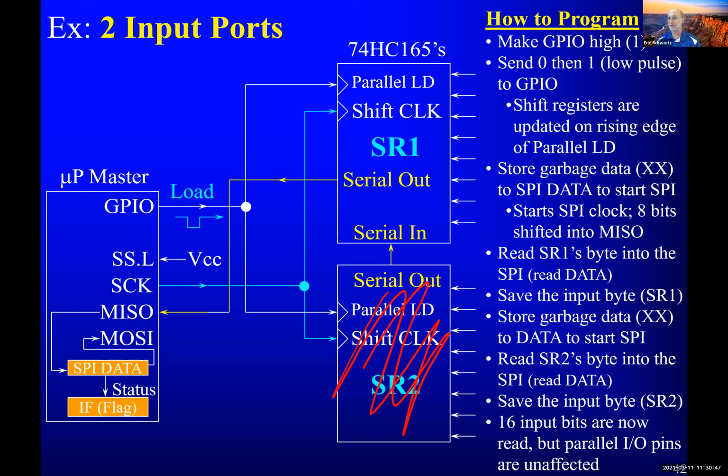What's the advantage? Well, you may not have a choice. You may not have EBI. And the other advantage is you only need 3 pins. Or 4 if you count. Well, 3 pins. So that's instead of 8 pins at minimum. Right? Minimum is the data bus. Now, those aren't additional pins because if you have a data bus, the data bus can be used in 100 different places. And you need all that address decoding. Here, you really just need 1 pin. And even if you have 6 of these, you only need 1 pin.